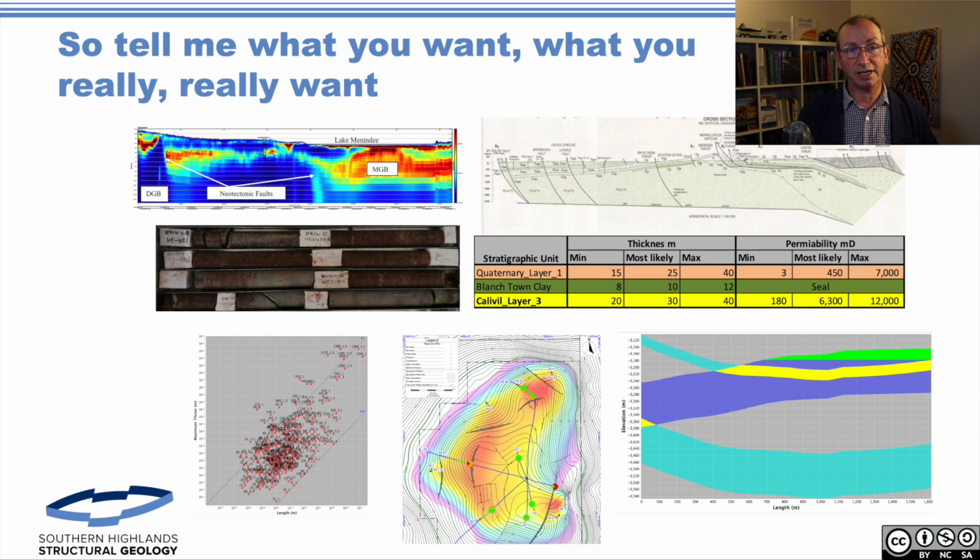We're putting together training courses to take this in a modular sense so that you can dip in and out of working out what's important and what isn't important. But fundamentally, these are the things. Show us your geophysics, use geophysics. Show us your cross-sections. Characterize your aquitards and thicknesses. Put maps with faults marked on them properly, with contours and tick marks on your contours.